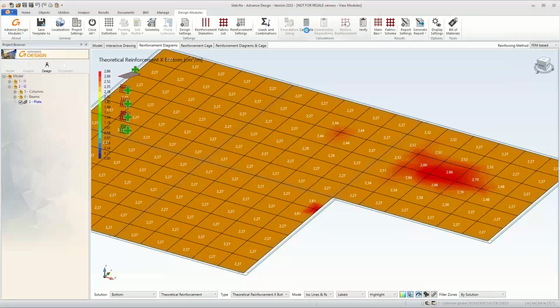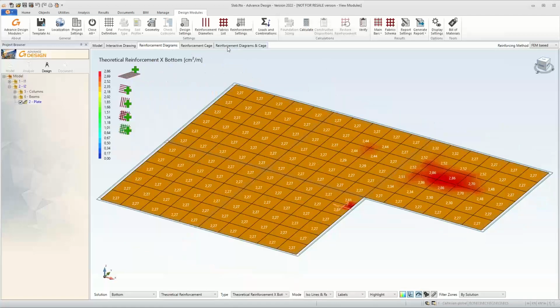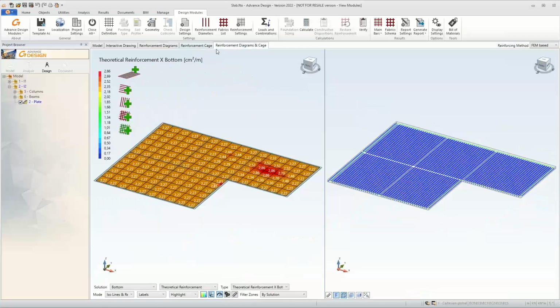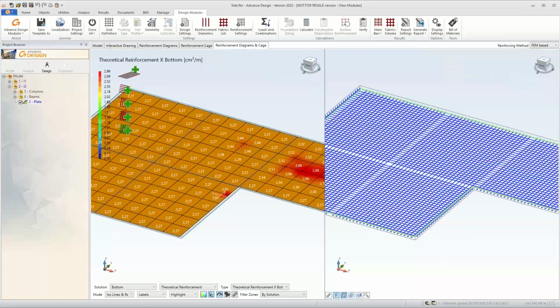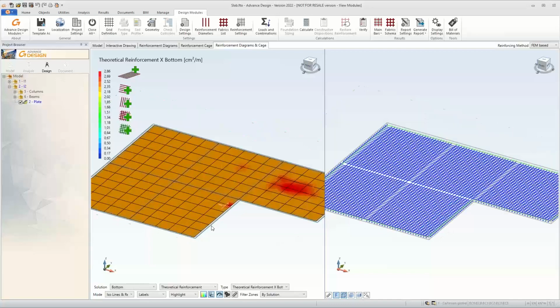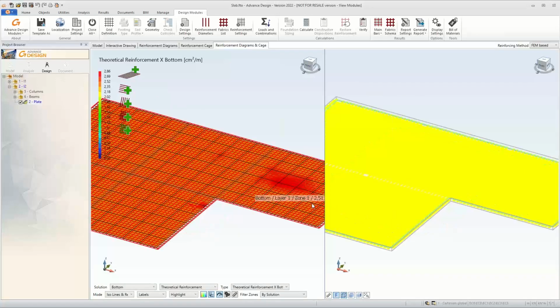It means that if I calculate that slab using those settings, I will select a better view. I get the automatically generated bottom and top reinforcement on the whole area using the maximum value of 70% of the maximum reinforcement that is on the slab.